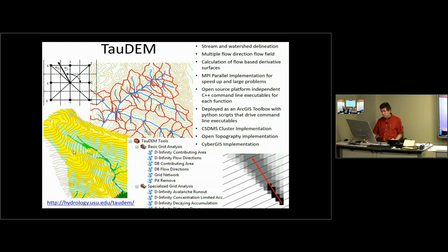If you proportion the flow between the downslope grid cells, it's going to spread out, so you've got some sort of dispersion going on, but on average the mass of the flow would follow perpendicular to the contours. If you limit yourself to one flow direction, you're either going to have the flow going straight up or straight down the 45-degree diagonal, and that's introducing a bias either to the left or the right.